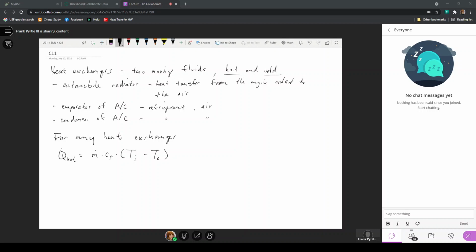And since it's a flowing fluid, the expression of the specific heat as C sub P, to represent changes in enthalpy, is what's required. So you'll see in your text, instead of there just being a C here, this will be C sub P, so that it considers that we can have a gas or a liquid moving through the heat exchanger. If it's a gas, we're definitely going to use C sub P, because there is a difference between C sub P and C sub V.